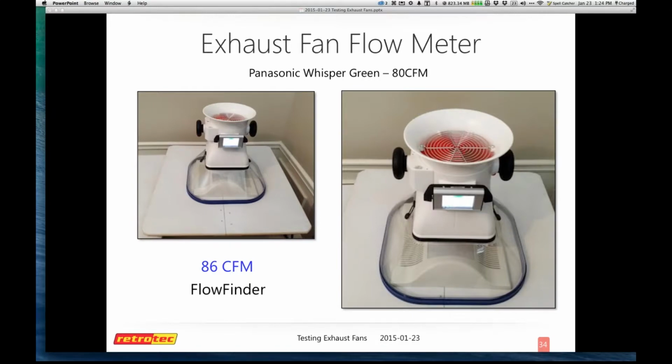So it will allow you to cover larger exhaust fans or a variety of systems, including a return up on the ceiling. And it comes with 2 pole connections if I want to do something on the ceiling and keep it up there permanently. And it has a variety of pressure taps on the inside for better reading throughout the system, and it's got one pressure tap over here on the top. So here it is by itself, so you can see how it works with the system in relationship with the DucTester. If you're interested in those, Retrotec sells those directly. They may be available with some of the other distributors.